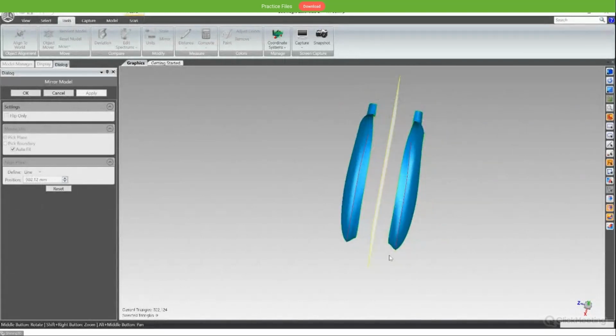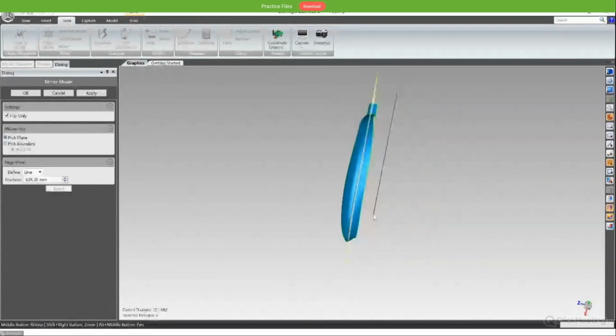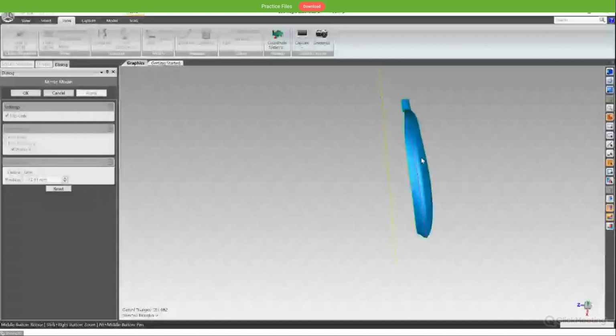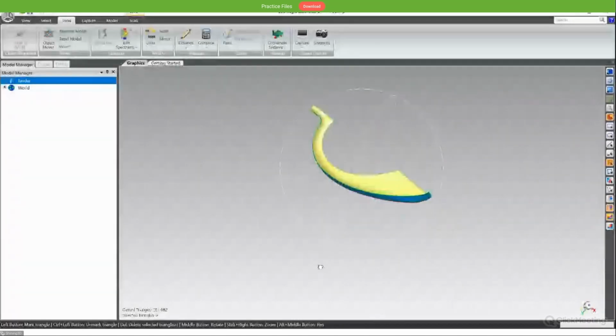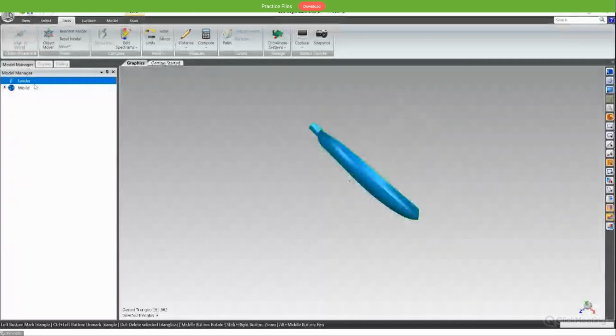Also, in the XScan software, like XScan HX V1.3 or XScan Pro V3.7 or later, we can also do a mirror function, but Geomagic Essentials can do more, which is it can align two parts, the original one and the mirror.